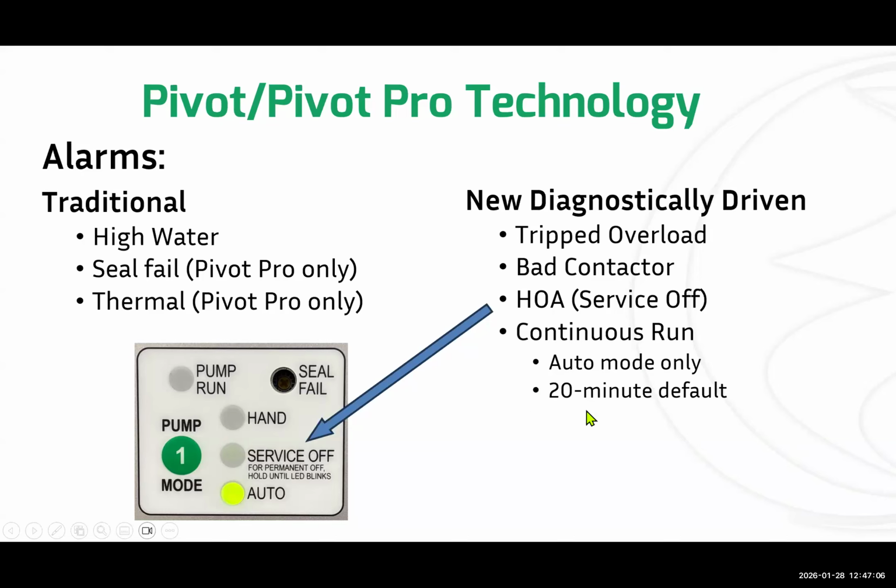But out of the box, we just know historically the projects that Zoeller is involved with, the vast majority of projects, a pump is going to kick on. It's maybe going to run for 5 or 10 minutes, and it's going to stop. Like it's going to complete a cycle. It's going to shut off, and then it'll queue up the next pump on the next cycle. So if a pump kicks on and it runs for 20 minutes, it will sound an alarm.